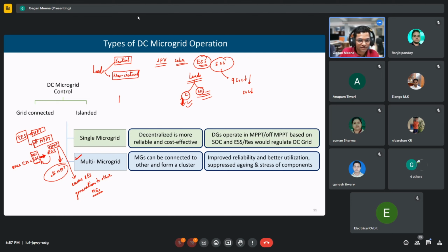And then the microgrid is connected to the main grid via a grid voltage source converter. This is a DC line. So this can act both as a converter, or we can say a rectifier, and an inverter. When will this voltage source converter act as an inverter, and when will it act as a rectifier? You tell. There can be power flow in both directions.